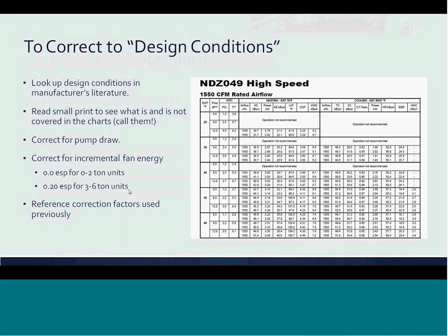So in this particular unit, there is also no accounting for pumping energy. So to accurately portray the performance of this particular heat pump at design condition, corrections will need to be made for both the additional fan energy by the ductwork and for the pumping energy. In addition to these heat pump system components, more additional corrections for airflow, water flow, and building temperatures must be made. Note up here in cooling mode that the entering air temperature condition is at 80-67, and that's not typically where most of our buildings will be performing or be required to perform.